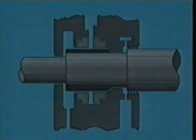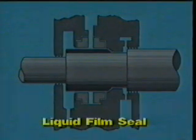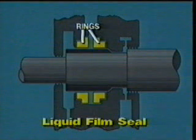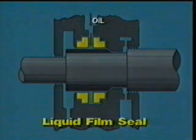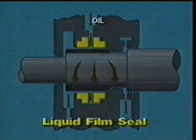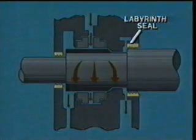On high pressure and heavy duty compressors, liquid film seals are the most common. A typical seal consists of 2 or more rings that don't rotate, but are free to float with shaft movement. Oil is injected between the rings at a pressure higher than the compressor suction pressure. This allows the oil to flow between the seal rings and the shaft, and then into the oil drains. Labyrinth seals guard against any oil leakage into the gas stream. Emission regulations sometimes require the use of liquid film seals. These seals provide a barrier fluid which prevents leakage of processed gas to the atmosphere.